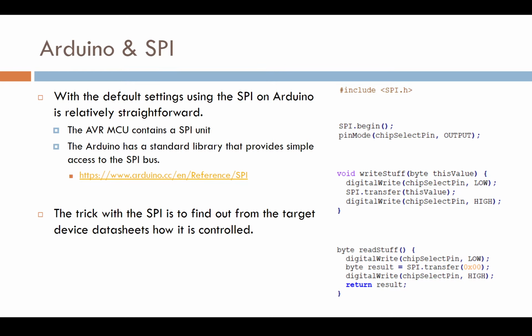Okay, so wrap up. Serial port, either real RS-232 or the extended version RS-485, with or without line buffering, connecting signals for all the data transmission from one device to another, as demonstrated on Tinkercad. Then we have the ASCII character set, which gives a nice way of sending human readable information, not just binary values, in ASCII coded data transmission, which is now more or less called UTF-8, 8-bit universal characters.